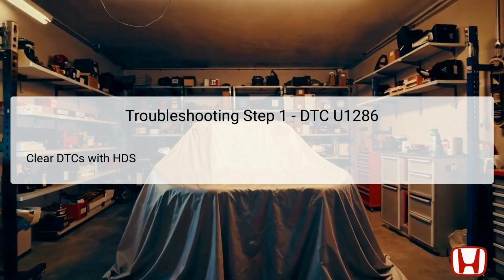The initial step in troubleshooting DTC U1286 involves using the Honda Diagnostic System (HDS) to clear any existing diagnostic trouble codes. This process helps in resetting the vehicle's onboard computers and can sometimes resolve intermittent issues. Once the codes are cleared, monitoring the system for fresh DTCs becomes essential. This is a critical first step, as it establishes a baseline for any further diagnostic procedures and helps eliminate false positives from previous codes.